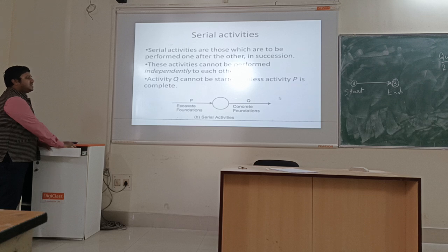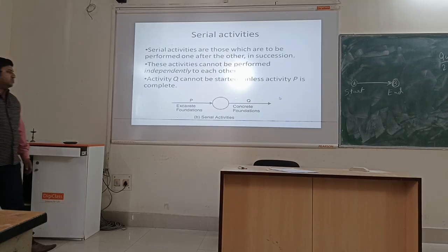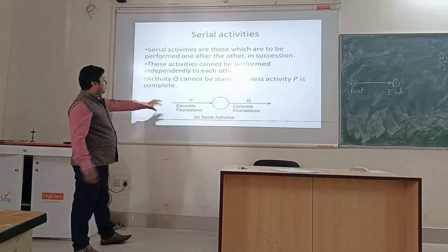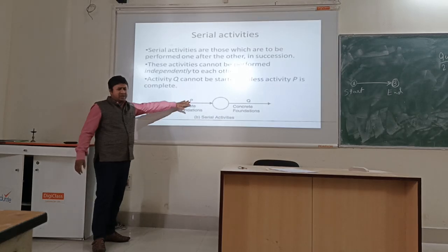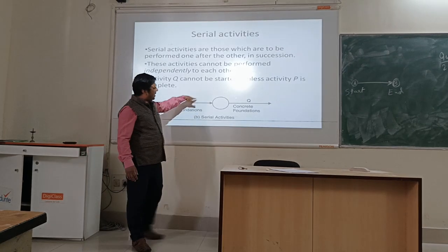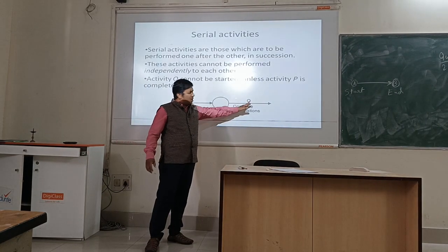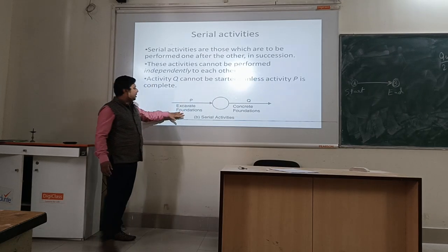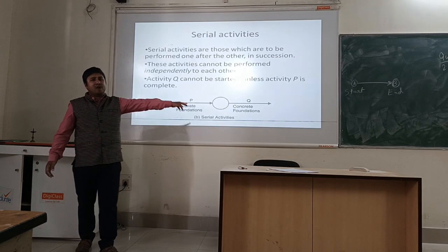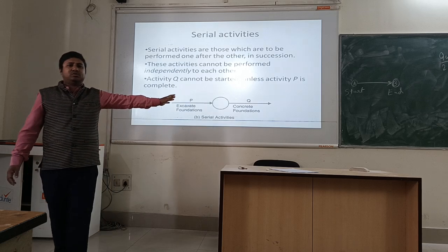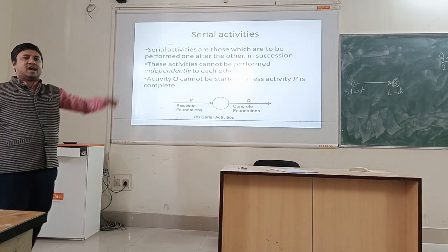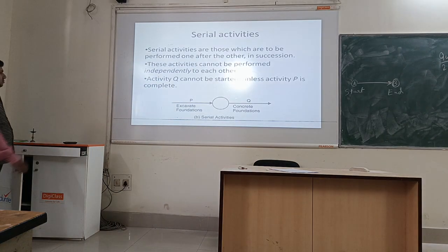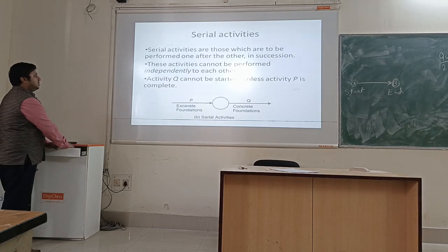Next are series activities. Series activities mean that once a particular activity, say P, is completed, only then can we proceed with the starting of the Q activity. Unless you excavate the foundation, how will you lay the concrete? That is why it is called a series activity. Understood?